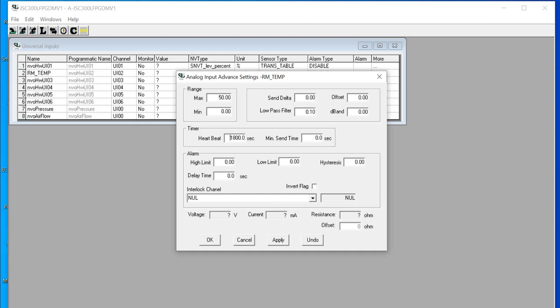At the sensor side, you disconnect the wire just to give power, then you measure the output. See whether the voltage is stable or not. If not stable, it's a sensor issue. If it's stable, then you connect the wire from one end to the other, and at the DDC end you measure whether the voltage is stable or not. If the sensor side is stable but the DDC side is unstable, usually the wire has some interference.